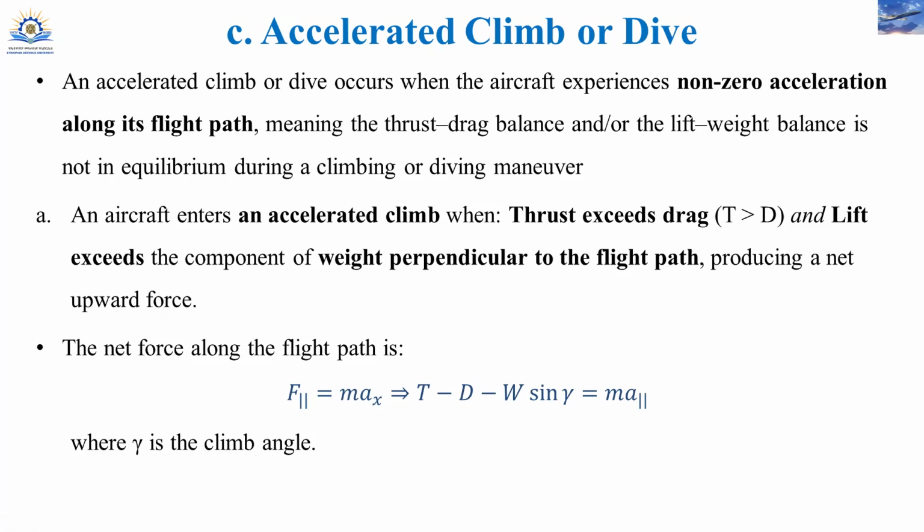As you see in your thrust or the drag curve, the thrust required and the thrust available curve, there are regions where we are using excess thrust. Because on the curve, you have this kind of profile. So if this is the thrust available curve, this is thrust required curve, but still at this point, you have excess thrust.